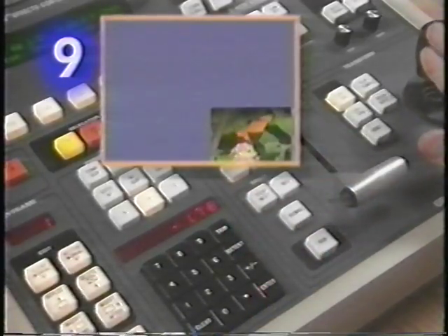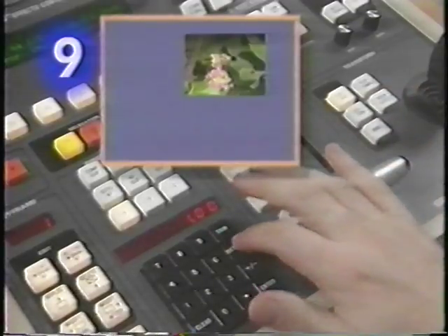You can use the detent function in the DPM-100 to quickly select from a limited number of fixed values rather than a continuous range. To demonstrate the detent function, select any transform function you wish to adjust. Select X, Y, or Z, and note the current value displayed. Now press detent on the direct entry keypad. The selected X, Y, or Z value will be changed to the nearest detent value.